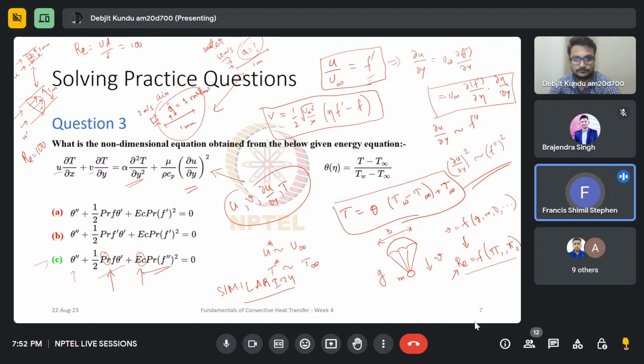So one more thing is, if we are doing a CFD analysis or anything for a bigger structure, if we make a prototype of that same structure in a smaller scale, will both the calculations be the same? Yeah. So if you match the Reynolds number, then the flow behavior is the same, even for the model as well as the prototype.